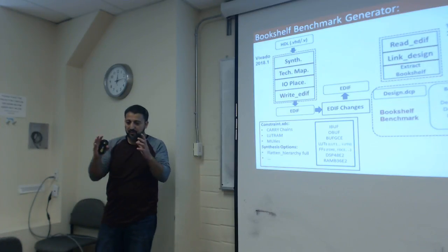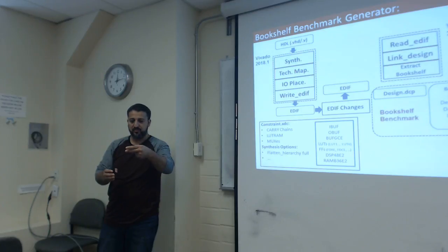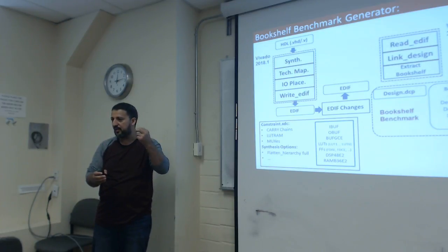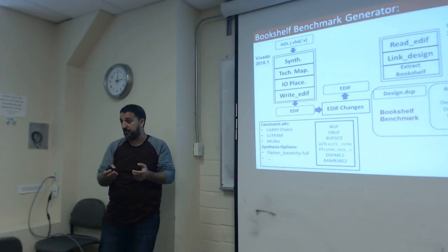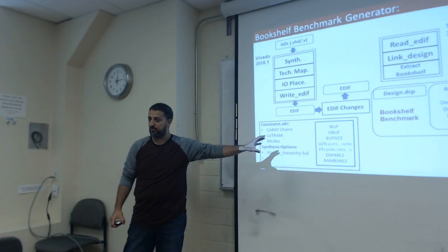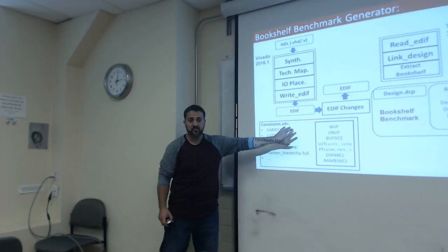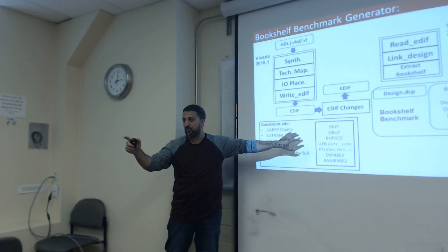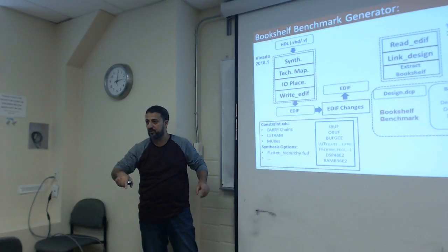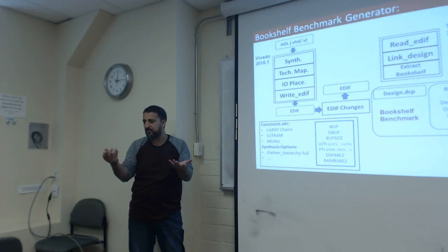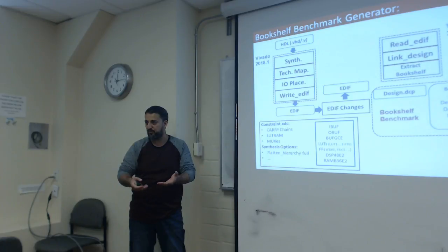Another thing is some of the LUTs will have two inputs, where one of the inputs is connected to VDD and ground, but it's in the circuit. What is the source for the VDD and ground? If we put it here in the FPGA, this is not true, because VDD and ground can be supplied from a switch. There is a source in the switch box that gives the VDD and ground. So we need to get rid of those and shrink the size of the LUT, because if you have a constant for one LUT, instead of 3 input LUTs, you can treat it as 2 input LUTs and so on.